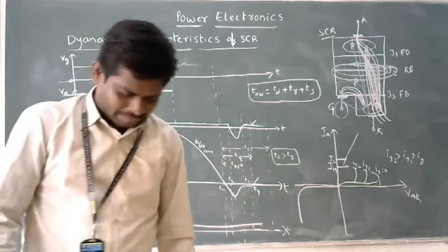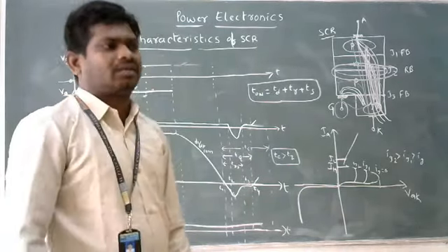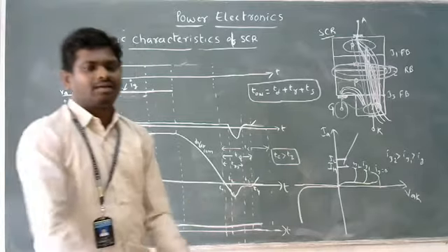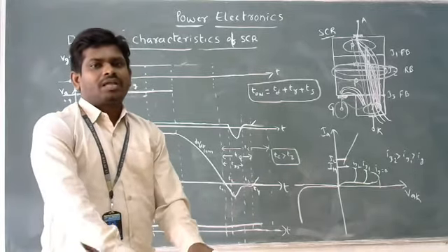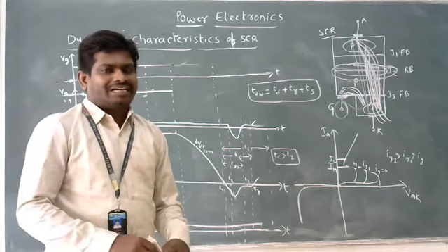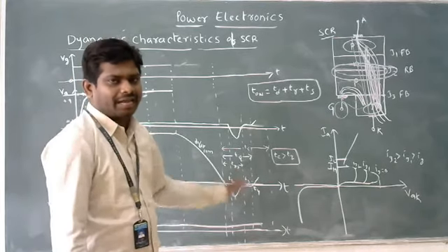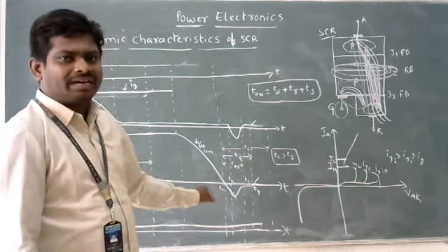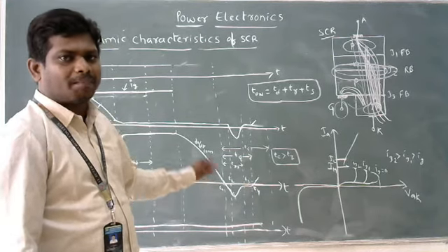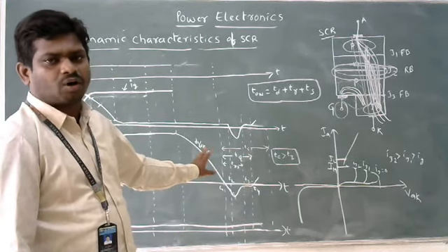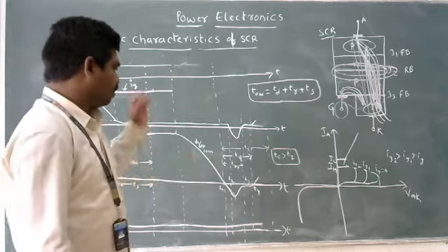Reverse recovery time means what? Whatever excess charge carriers are there, the device must remove them. For that, the device takes some time, called reverse recovery time. It has to come back into forward blocking state. That is what we call reverse recovery time.